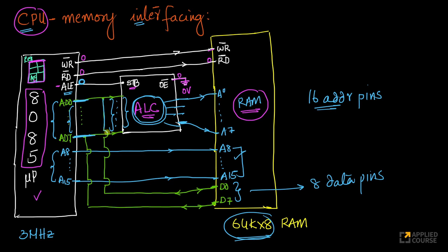When we draw a wire going over another wire like this in electronics, it shows that the two wires are not touching each other. So the AD0 wire gets connected to D0, and your AD7 wire gets connected to D7. And when ALE is 0, look at this, what gets passed here? Data, not the address.